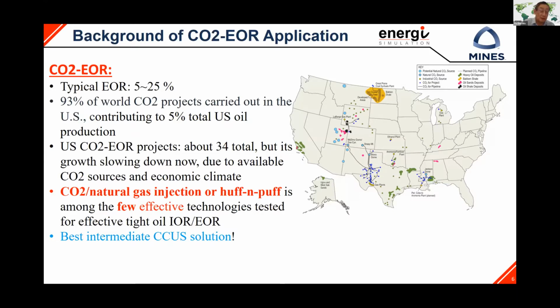The results show the only EOR approach that works for tight oil reservoirs is gas injection, huff-n-puff. Another benefit, discussed by a previous presenter, is that CO2 flooding or CO2 EOR operation is the best intermediate CCUS solution. This is an important area for the near future of the oil industry.